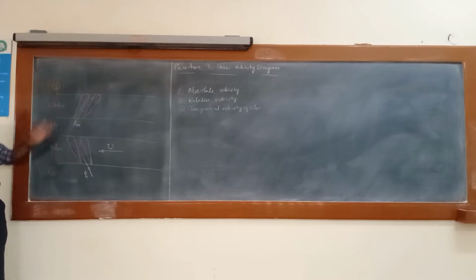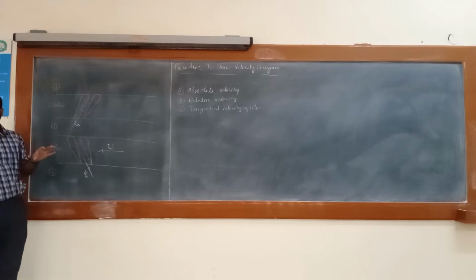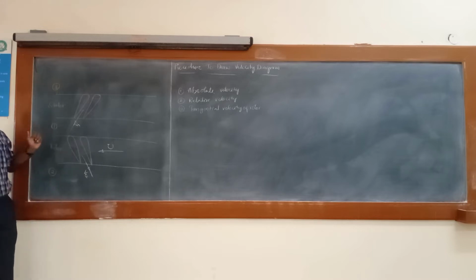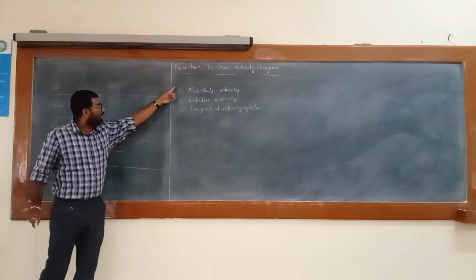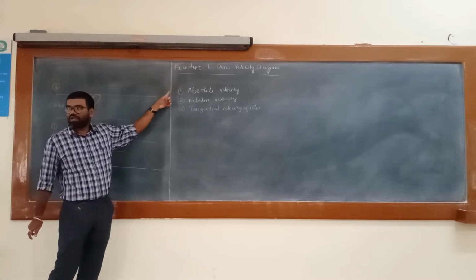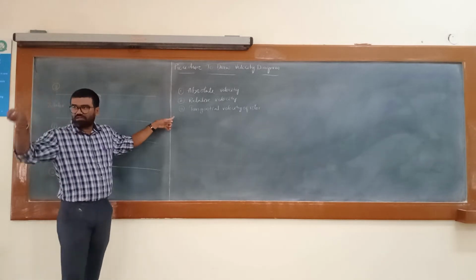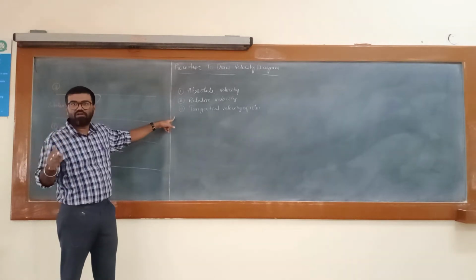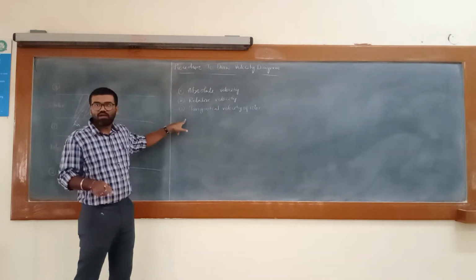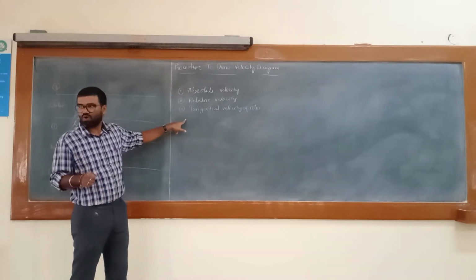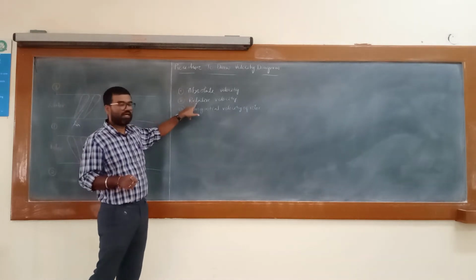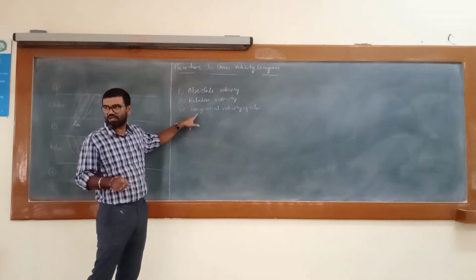Out of these three locations, we first need to decide where to draw the velocity triangle. We can draw it at the location where we get all three velocity components, because the three sides of the velocity triangle are formed by the absolute velocity, relative velocity, and tangential velocity of the rotor.